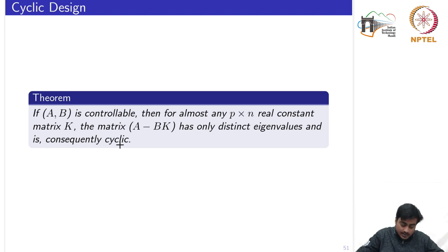So here we see the straightforward benefit that in the Lyapunov based design, we need to select the matrix K bar to ensure those two strict conditions. But here we had seen that for almost all V vectors, the pair A comma B times V is controllable.